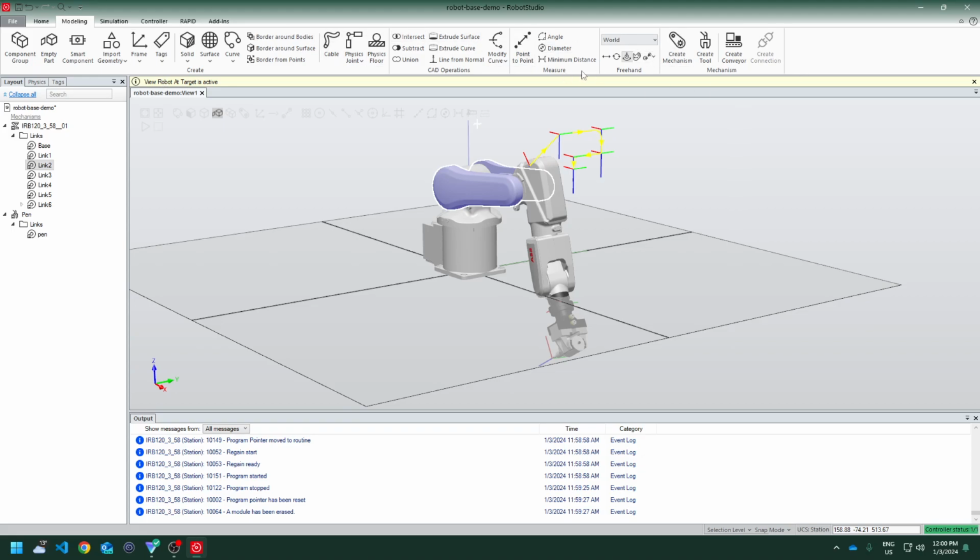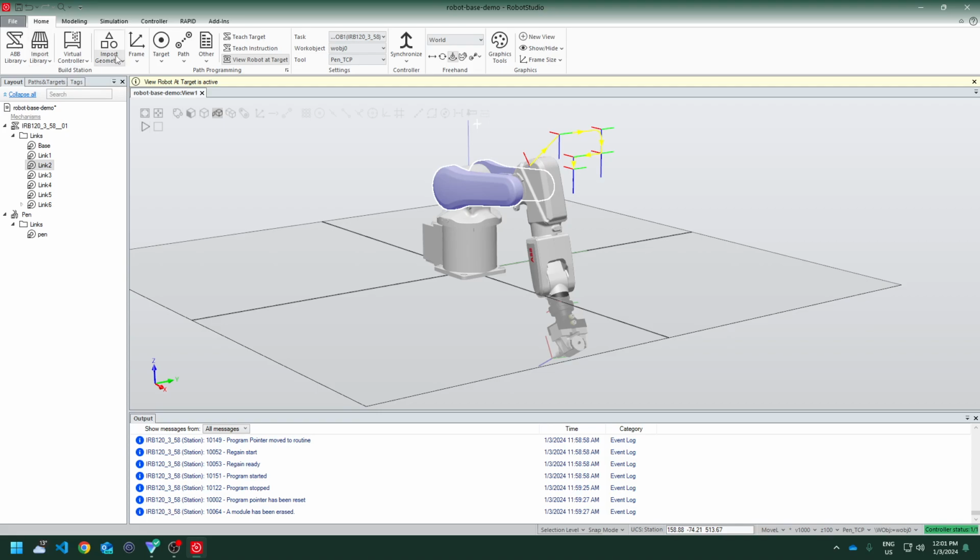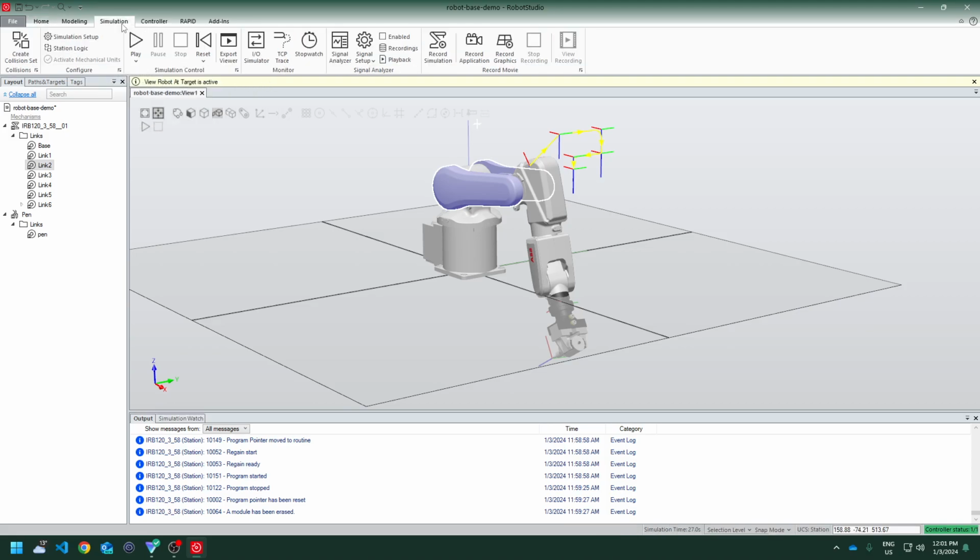If you're doing relatively simple modeling, yes, you can do it in RobotStudio. It's gotten much better over the last couple of iterations, but my advice is to fire up SolidWorks, create whatever you need, and then import the geometry using the STL or STEP files. I'm not sure which; there are various different types supported.